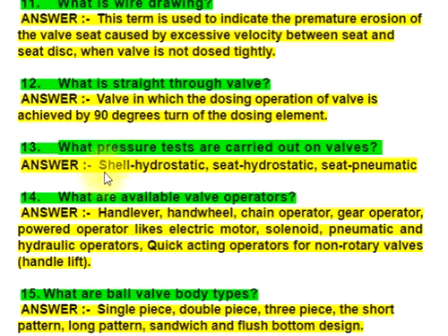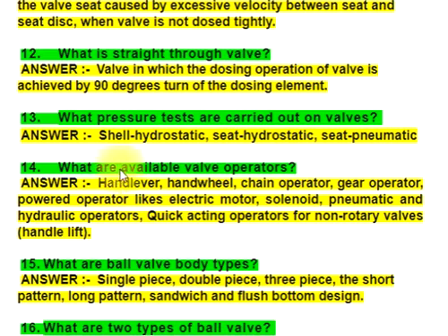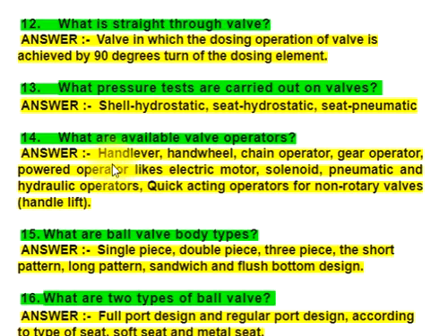13. What pressure tests are carried out on valves? Answer: shell hydrostatic, seat hydrostatic, seat pneumatic. 14. What are available valve operators? Answer: handlever, handwheel, chain operator, gear operator, powered operator like electric motor, solenoid, pneumatic and hydraulic operators, quick-acting operators for non-rotary valves, handle lift.